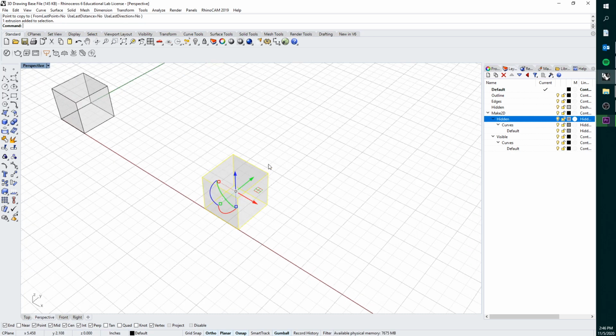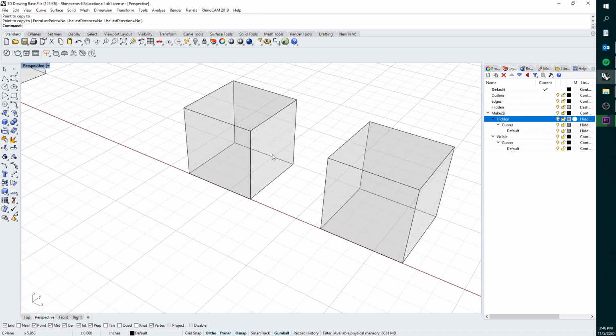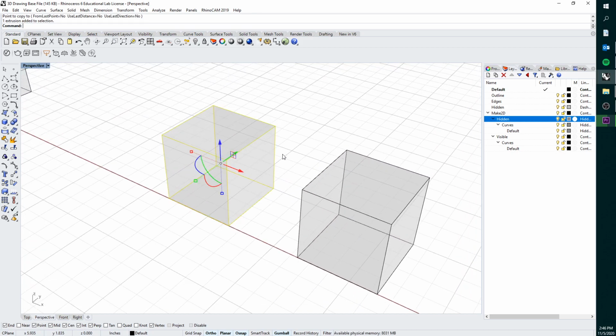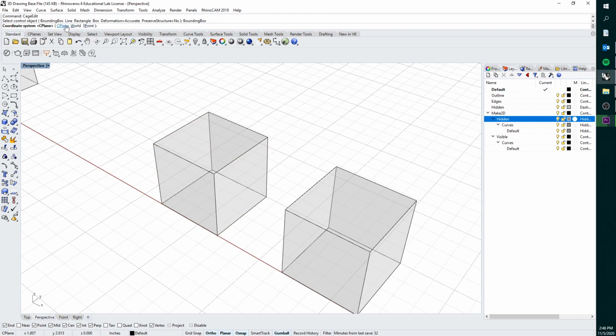So the main thing that has to stay here is this basic elevation view in order for it to be a true elevation oblique. So let's go ahead and do a cage edit on this, and then we'll do a bounding box. Actually, I'm going to copy this out. So I'm going to do maybe 2 different types of versions here of just different ways you can think about this. So if we take this and then we do a cage edit, again, bounding box, we're going to take a look at C-plane. Our point count should be 2, global.